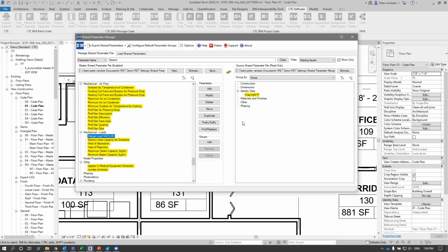So we are in fact able to take this and, okay, hypothetically I have 3 shared parameter files. I can say, okay, this is going to be my master, and then I can load up one of the other ones over here, and then just drag over the ones I need, drag over the common ones, and then load up the other one, and again, drag over the common ones, make sure that they fix any conflicts that we may have, look at what the unique ones are, what's the same. I can work with all of that. But now I have this glorious, amazing single shared parameter file.